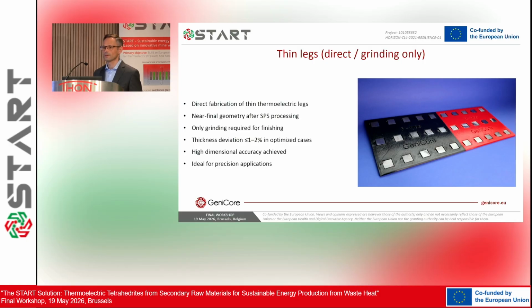Such an approach improves the parallelism and limits the roughness of the surface, but of course, because of the thickness of graphite, separators influence the effectiveness of using the graphite die, because the total height of such a system increases.